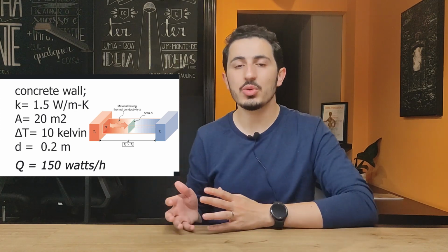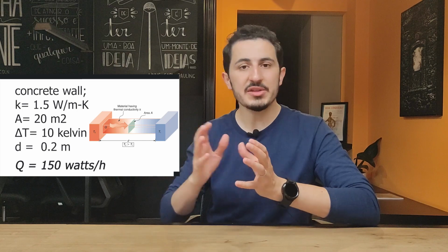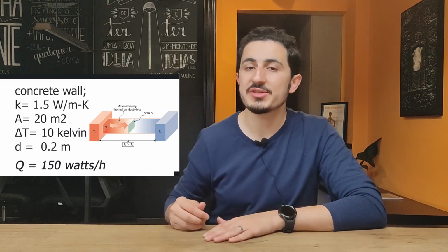Which means, of course, looking at the equation, if we want to reduce this heat transfer, we should reduce the U value, which means using more insulation materials. These values will make more sense in the next chapters when we talk about the energy performance of the building and look at a practical example. And as a conclusion, if we use the appropriate building materials with the appropriate insulation materials with the right U values, we can limit the heat loss from our building, which saves us more energy, and we can keep a comfortable ambience for the occupants.